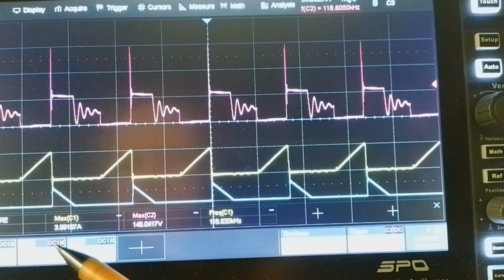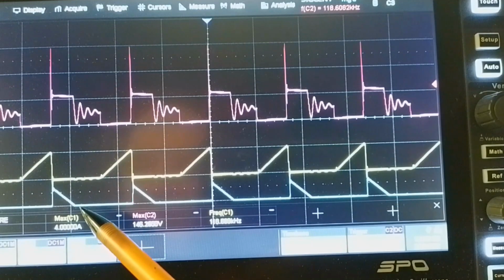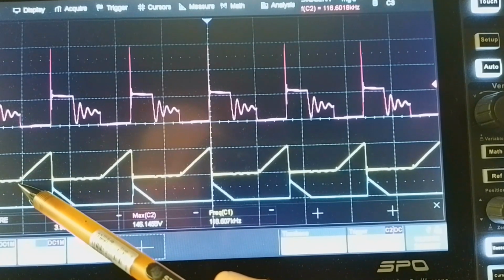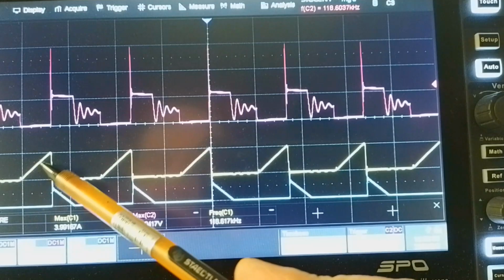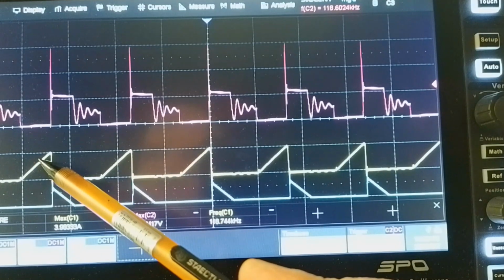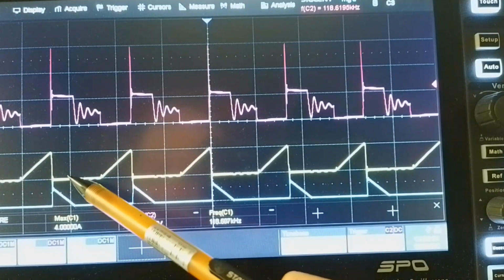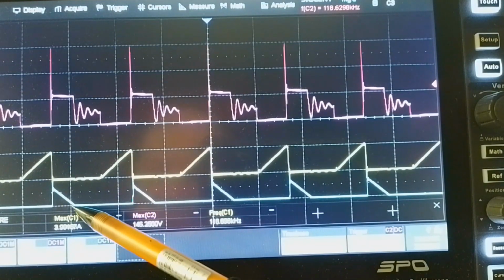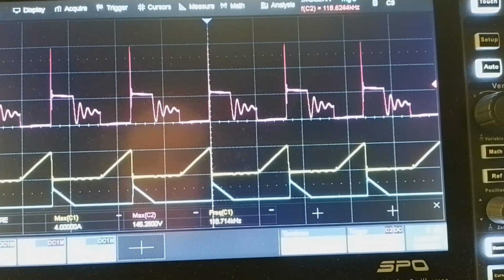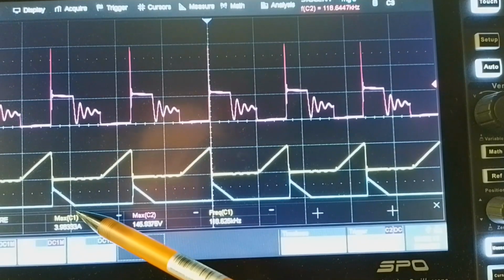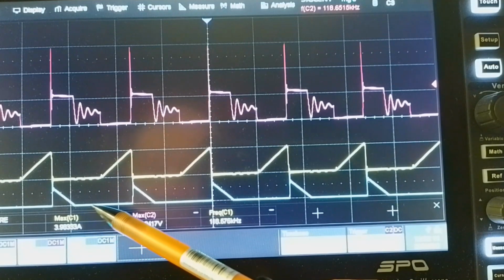So in this mode, flyback is in discontinuous conduction mode, which means that first we charge magnetic flux in the air gap, and after that we discharge it completely. So after discharging there is no magnetic flux and energy in the air gap left anymore.